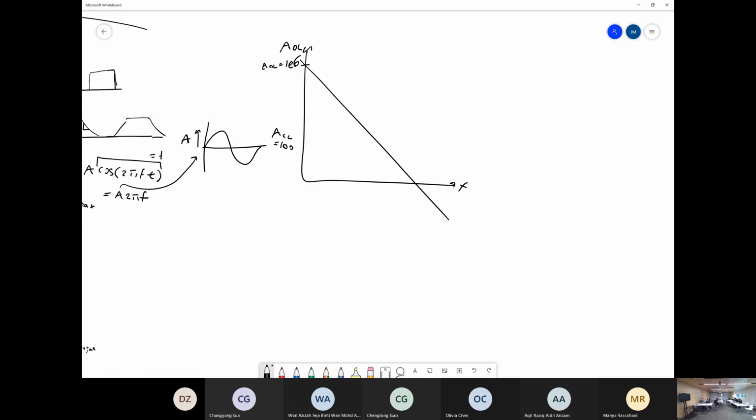What I'm going to have, intuitively, is if I close the gain, my gain is going to look like this now, right? But what's my bandwidth going to look like? Is my bandwidth going to go off to infinity? Well, no, it's going to look like this now, right? So I'm going to get effectively more bandwidth. Say if I had ACL equal to, say, 1,000.